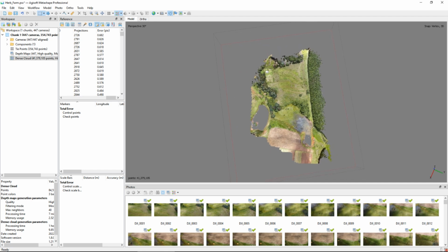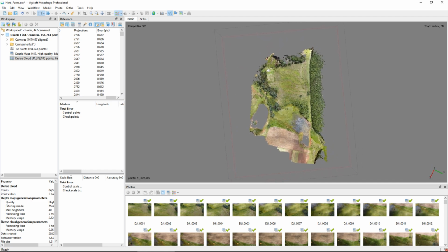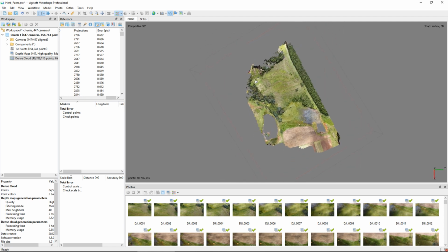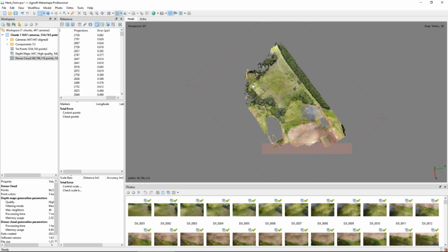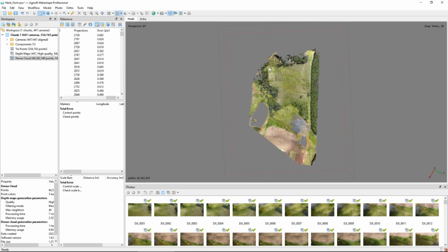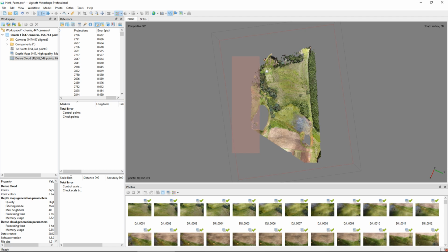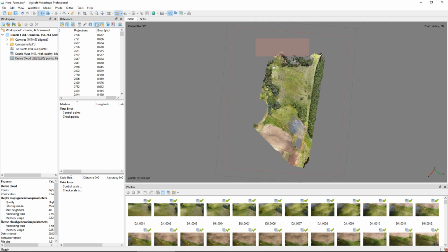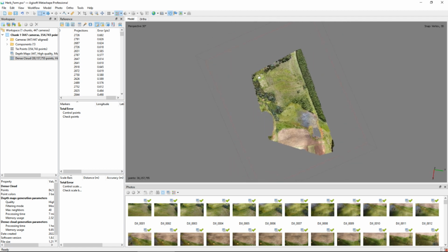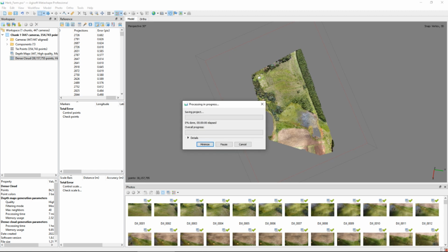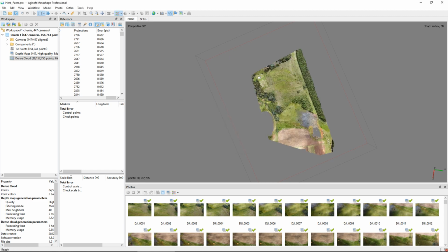Look through your point cloud one last time, confirming that all the erroneous or rogue points have been cleaned up. If they haven't, you might want to manually delete them. Here I am just aligning and cleaning the edge data out because it's unnecessary for my project. Always remember to save your project after having applied any new settings or run any new processes.